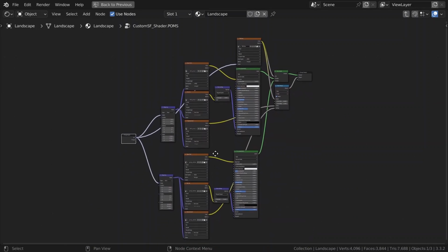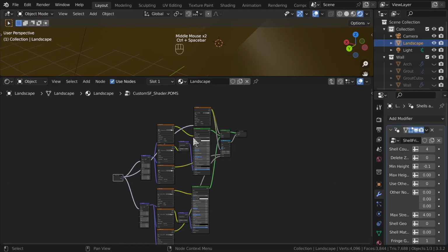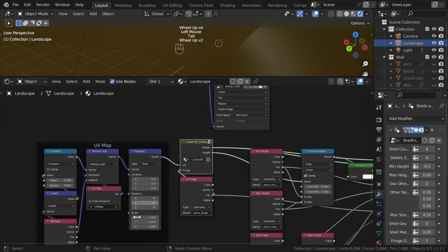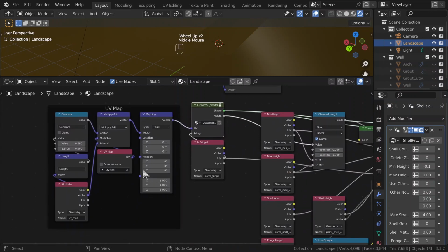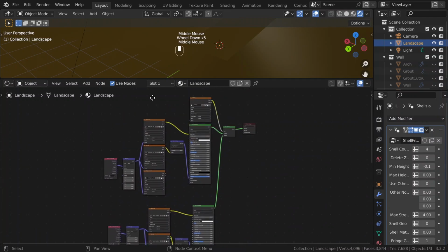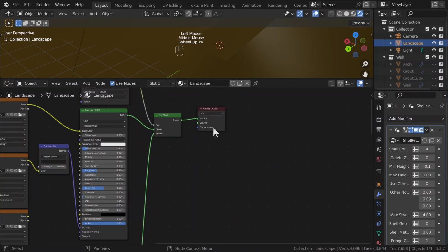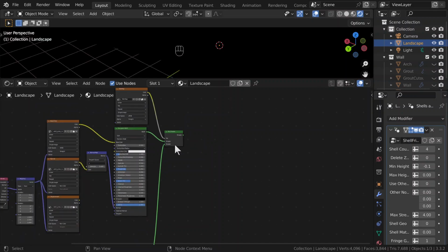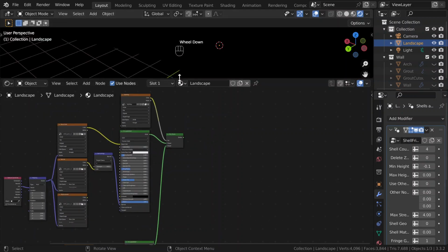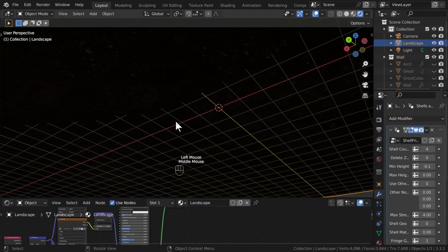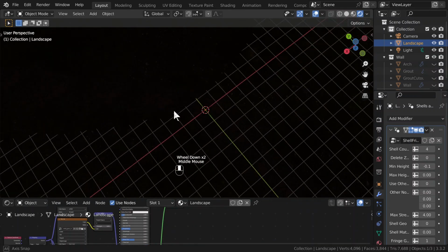Good. But when I go to rendered view, I can see that it's still not right. I need to do a little bit more fixing on the outside, so I press tab to exit this node. The current setup is not looking too bad, but when I zoom out and look up, I see that the old setup still has a material output that's interfering with the new setup. When rendering Eevee, this should look completely black on one side, at least.